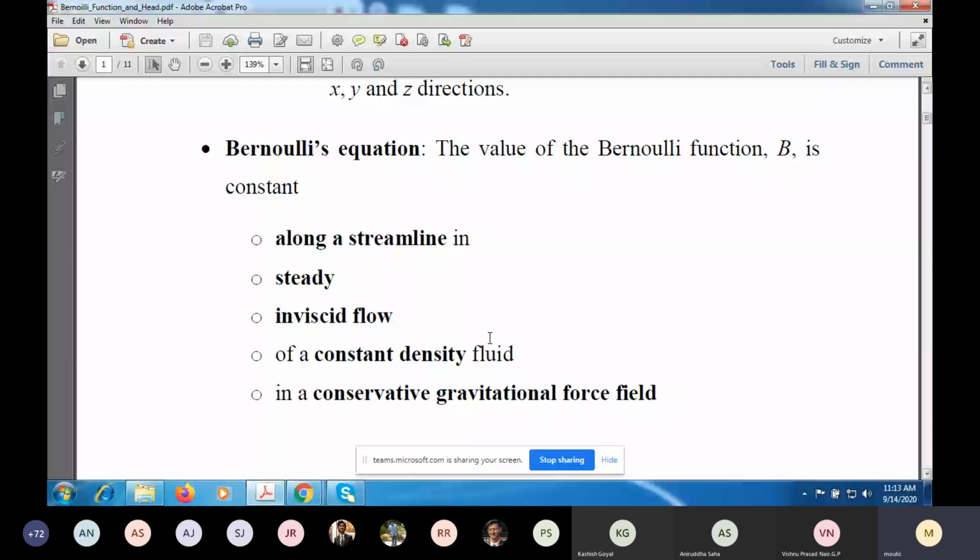You say that tau xy is mu du dy for a situation where there is only one component of velocity in the x direction which varies with y. But suppose the velocity distribution is uniform. In that case, what is du dy? The value is 0. So what is the shear stress due to viscous effects? That is mu times 0, which is 0.